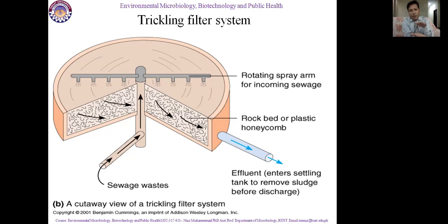Number one, it will support the presence of the microbial communities. Microbial communities will adhere there, they will proliferate, they will grow, and they will increase their mass, and they are active aerobically, and the incoming organic material will be decomposed on the surface of the sand by microorganisms. So pure water will only travel downward, because the sand will stop all types of material,